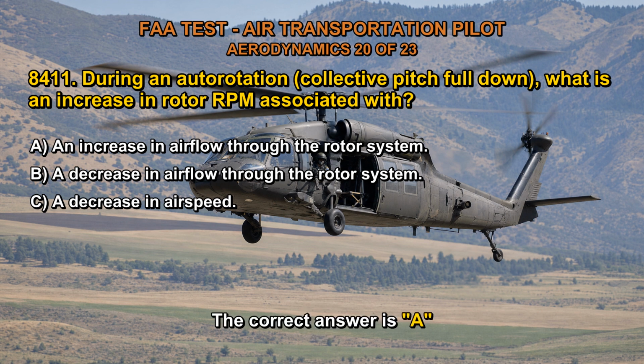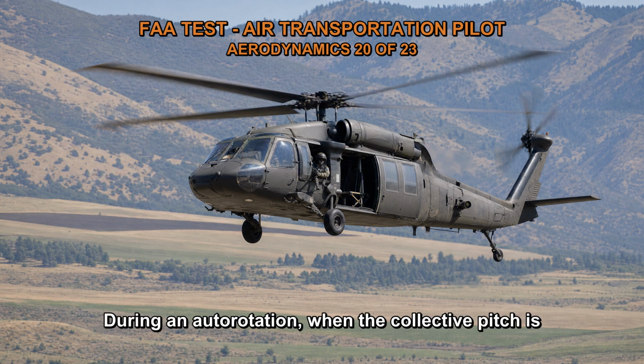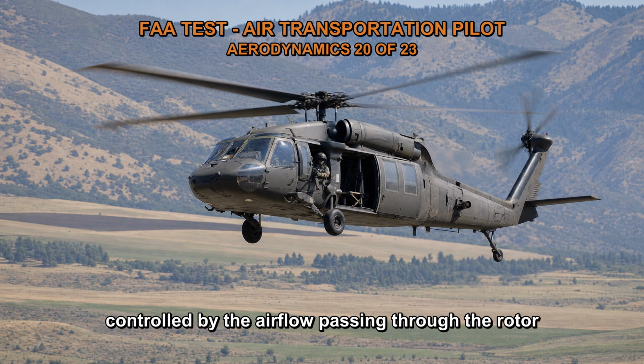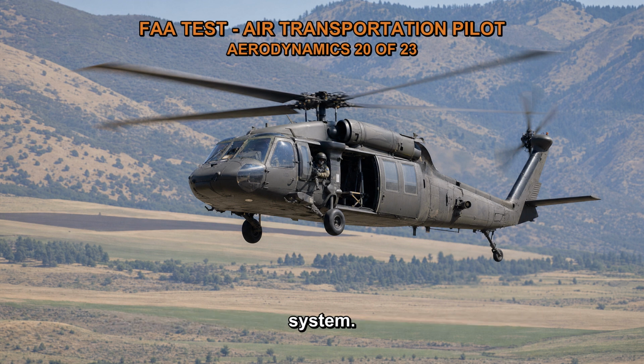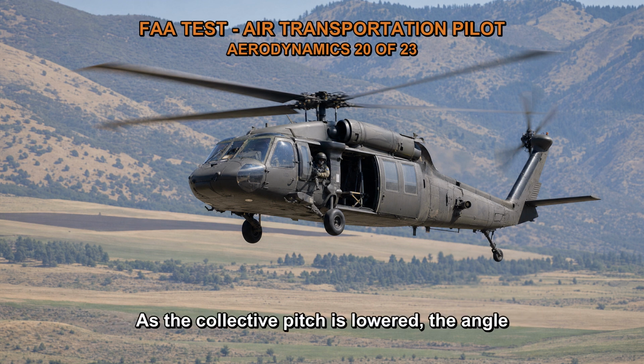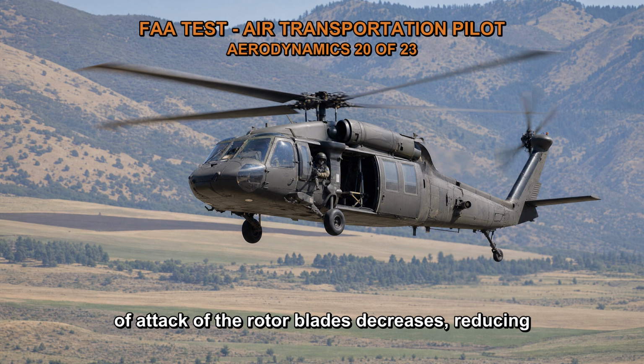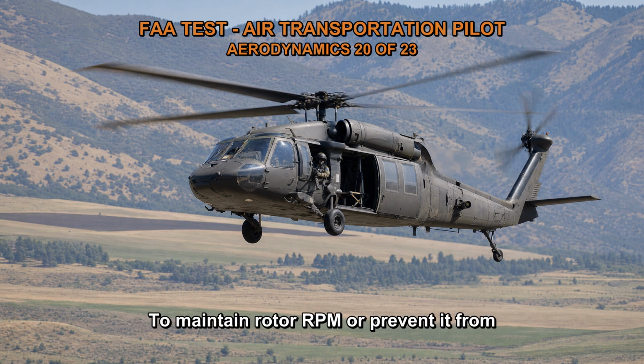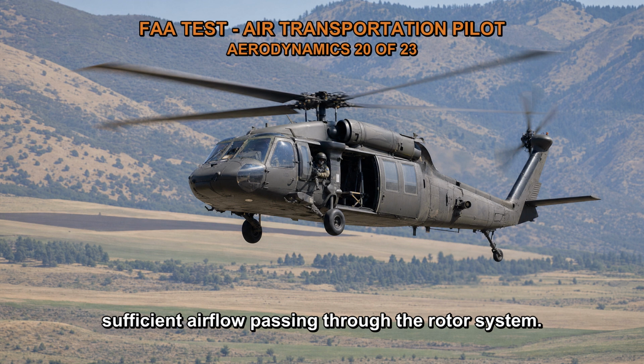The correct answer is A. During an autorotation, when the collective pitch is fully down, the helicopter's rotor RPM is primarily controlled by the airflow passing through the rotor system. As the collective pitch is lowered, the angle of attack of the rotor blades decreases, reducing the drag and allowing the rotor to freewheel. To maintain rotor RPM or prevent it from decaying too rapidly, it is essential to have sufficient airflow passing through the rotor system.